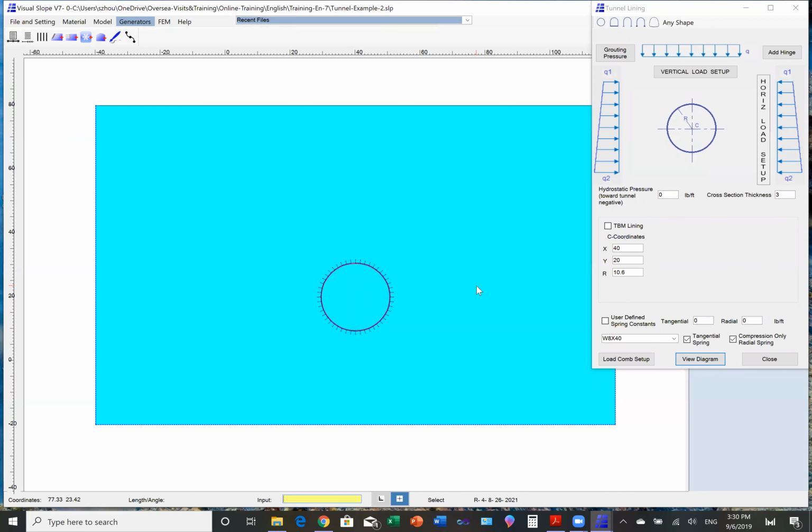However, for TBM segments, between the segments there are hinges, elastic hinges. Some designs you can consider. If you make it simple, you can just reduce the overall bending modulus, or you can do each individual considering the hinge elasticity.